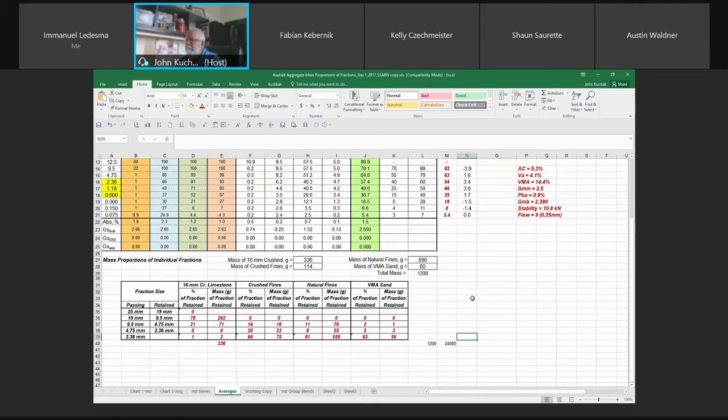Based on the sieve analysis standards, it's all rounded to 0.1 except for the 200 sieve. If it's less than 10%, round to the nearest 0.1. If percent passing 0.075 is less than 10, you show it to 0.1%. Everything else is 1%. If your percent passing 0.075 is 15.2, you would report it as 15. And that's only applicable to the percent passing 200.